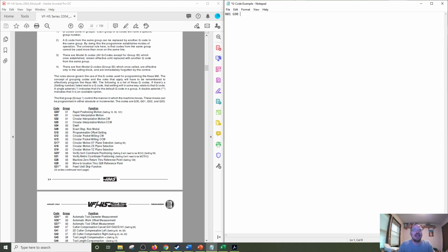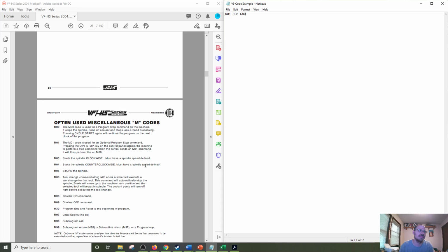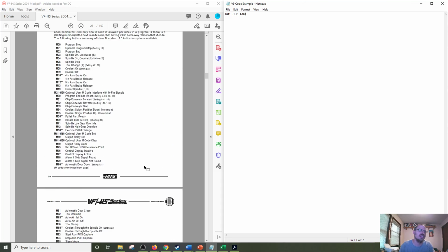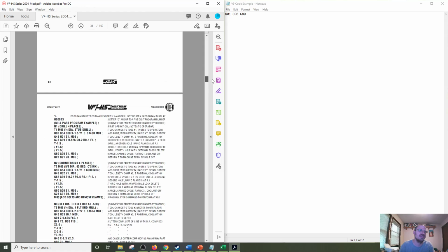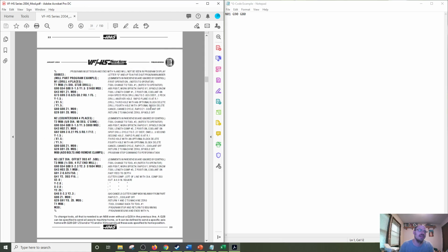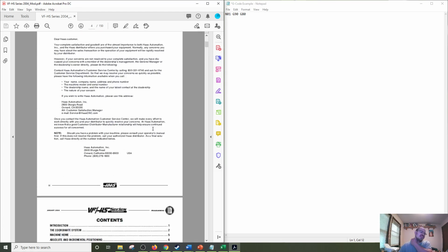And there is, I'll talk a little bit about it. We don't necessarily need it. Sometimes they run G80, so it's one thing you tend to see, and I think there's an example in here that does a similar function. What G80 does is cancels any canned functions. So canned functions are exactly kind of what they sound.